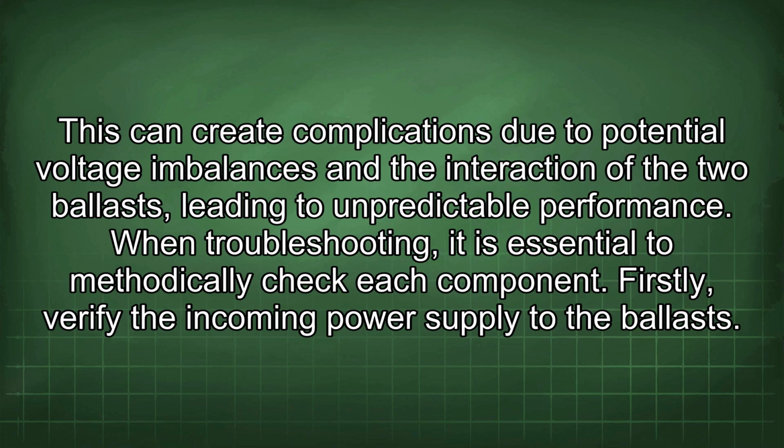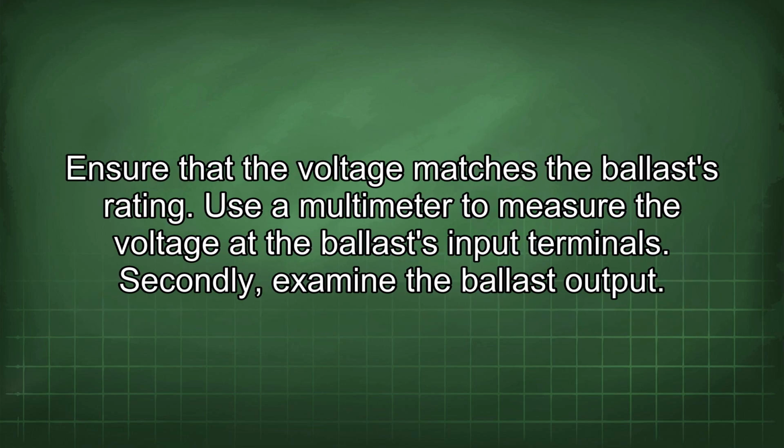Firstly, verify the incoming power supply to the ballasts. Ensure that the voltage matches the ballast's rating. Use a multimeter to measure the voltage at the ballast's input terminals. Secondly, examine the ballast output.